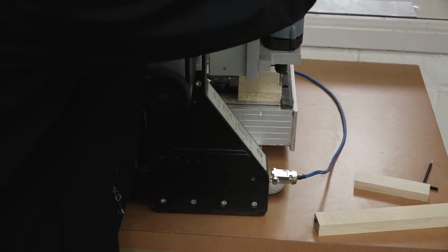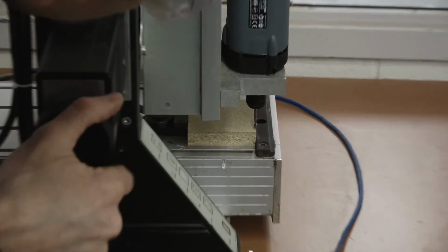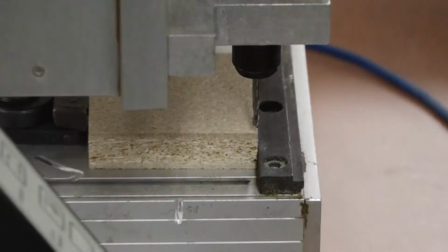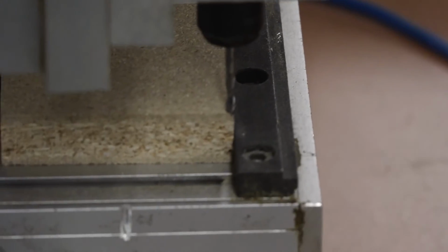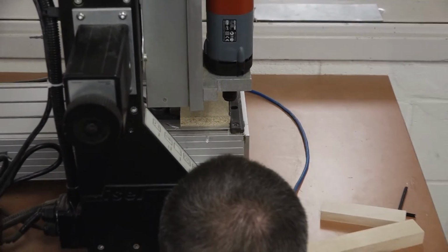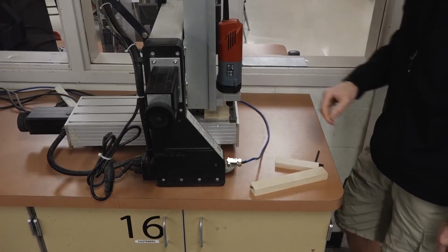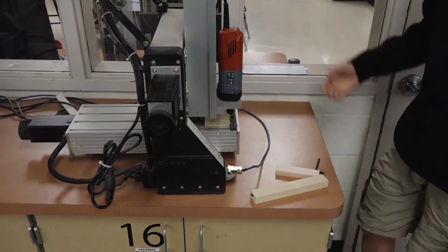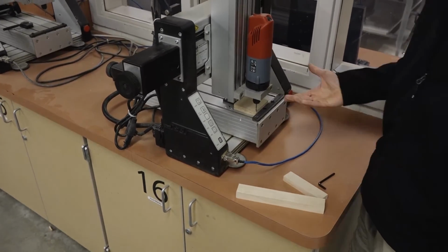Usually it doesn't take this long. I had everything out of the way so that I could take some pictures this morning. So what you want to be sure to do is get down here and look at the bit and get the center of the bit over the side. And then I'm going to do the same thing. I'll be in your way, but I'm looking this way. The center of the bit is now over that corner, and it's just touching the corner. Okay? And now, for the most part, we're ready to mill.